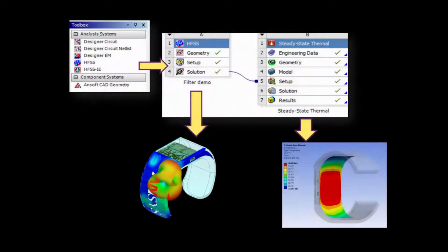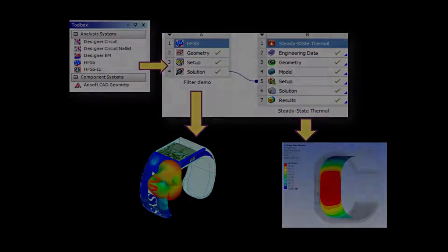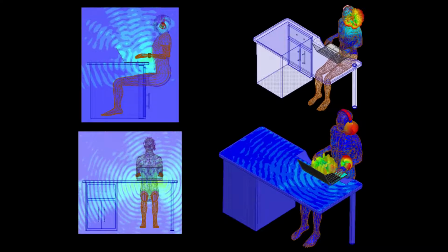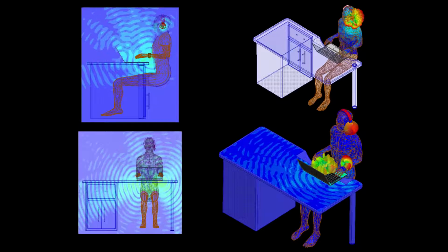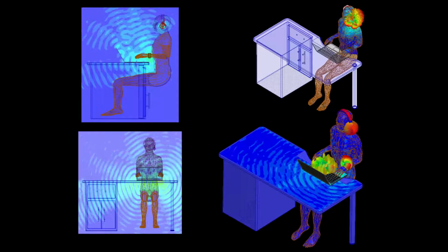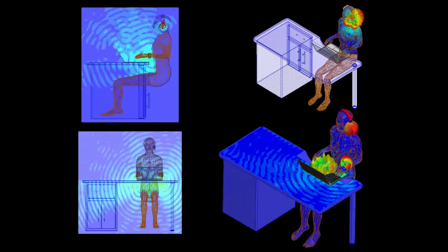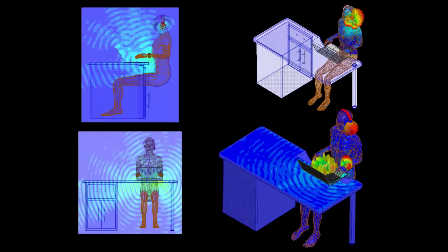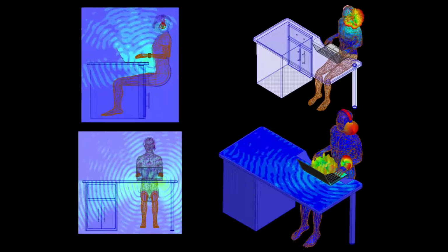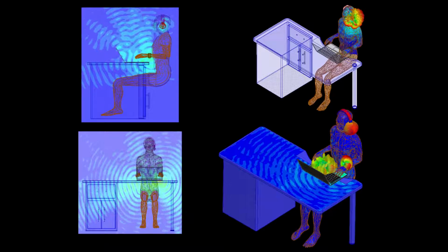The watch must not get too hot, and simulation can be used to predict the operating temperature. Here you see an electromagnetic analysis of the board coupled to steady-state thermal analysis to ensure that excessive heating is avoided. What's more, you can test the performance of your IoT device in a realistic environment. Here you see the wristband added to a human body model. A Bluetooth speaker was also added to model a receiver and the performance of the antenna in the vicinity of other electronic devices. The simulation includes the entire room to test the performance of the wristband under realistic electronic environments.